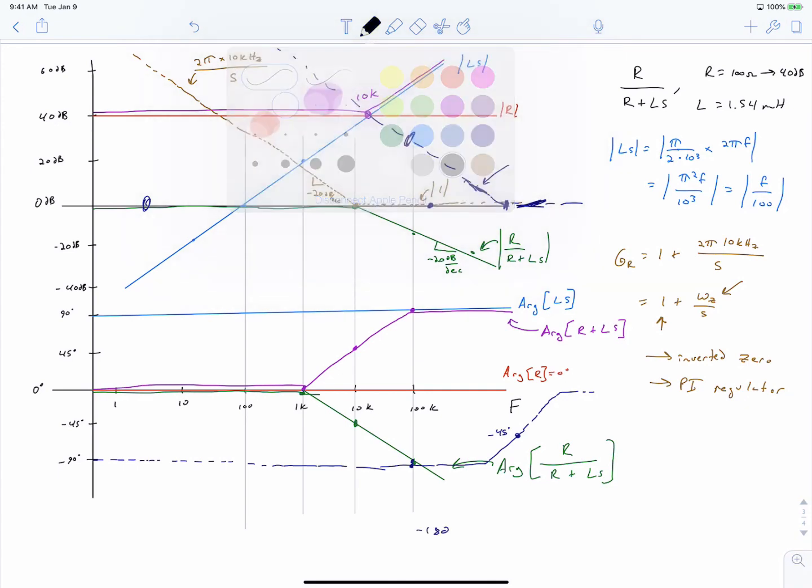So if we show down below what our phase angle is going to be for this final loop transfer function, it would be something like this. So right here we start to decrease as we're adding our two transfer functions. We get to negative 180 degrees. And this is where we go unstable, because this is the gain crossover point, or the GCF frequency. So in other words, our phase inversion frequency is occurring at a lower frequency below our GCF frequency if we pick omega z to be too large.